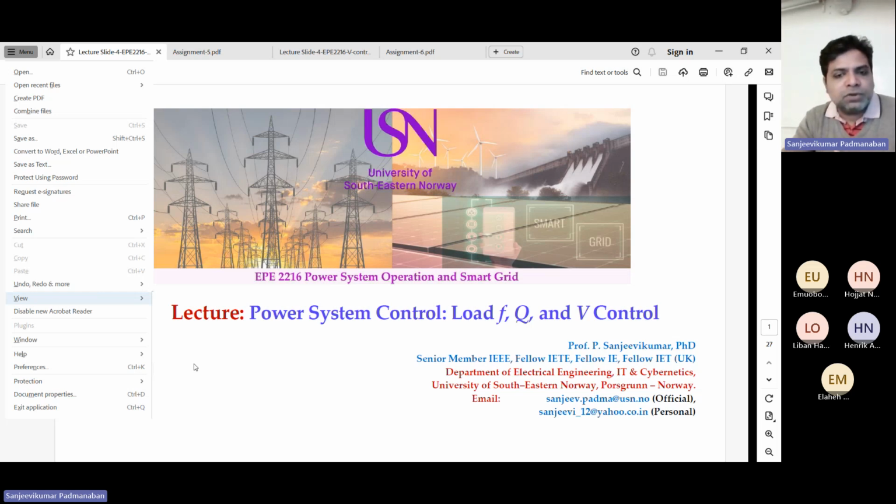So it's a different margin of operation, perturbation conditions. So every time the system needs to update its gain value for the gain parameter and for the integral parameter. If the controller is designed with the derivative, then the derivative gain. So we have three types of gain: gain for the proportional, gain for the integrator, gain for the derivative. So the gain needs to be upgraded or adjusted based on the operating conditions.